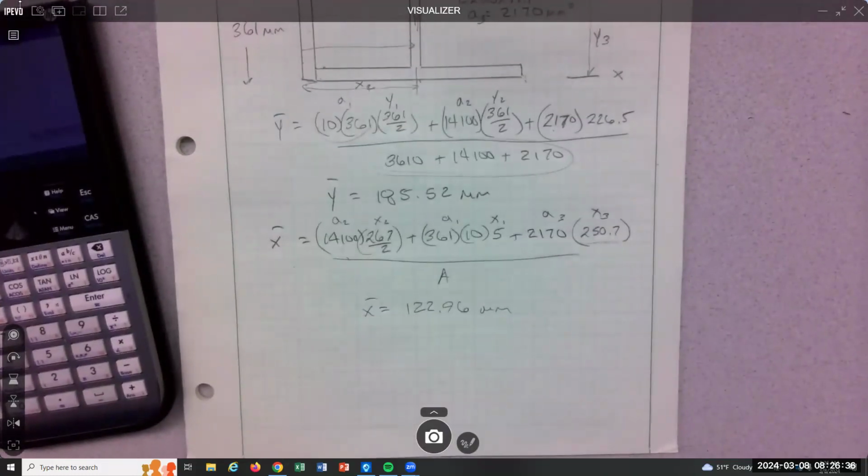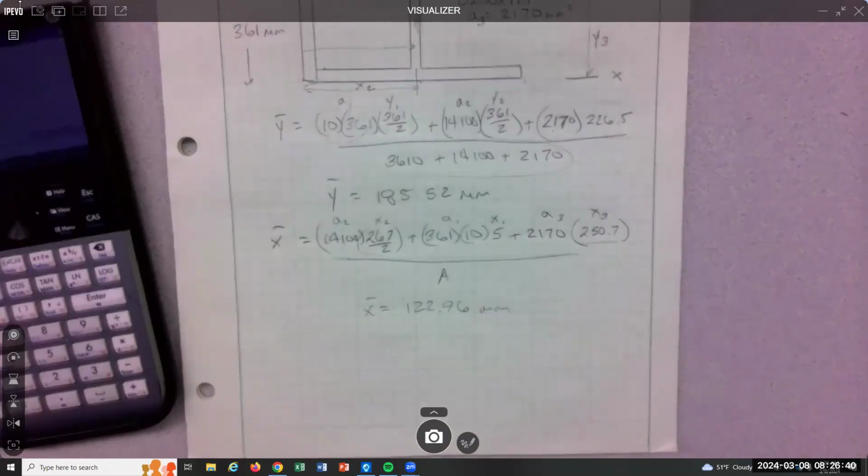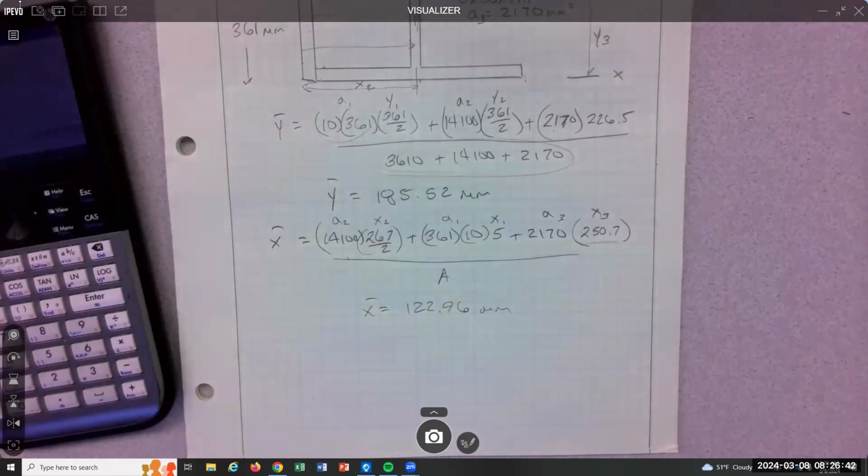That gives us the location of the neutral axis, both directions. So when we do biaxial stress, we need to calculate an inertia about those axes, the combined X and the combined Y. So next term, in strength of materials, we're gonna run this Mc over I. Inertia is very specific to the location of an axis.